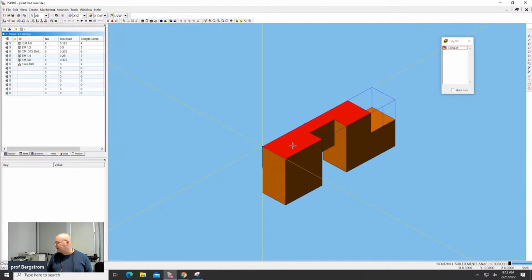The other thing is this plane right here. That's going to be lined up with that edge of the stock material also. So if we shift the workpiece down and right a little bit, is the stock material wider than the workpiece? What's the dimension from here to here? Do you know? All right, if we don't know what that dimension is, we can pretty easily get it.